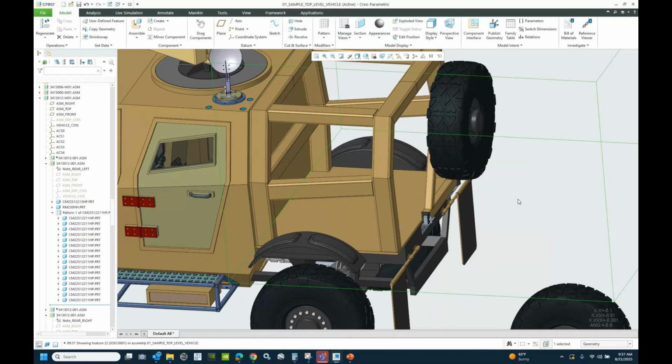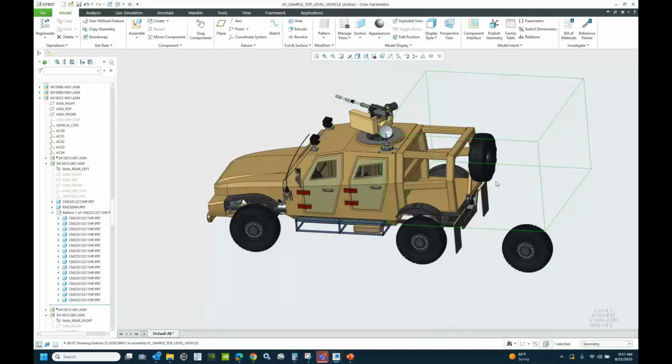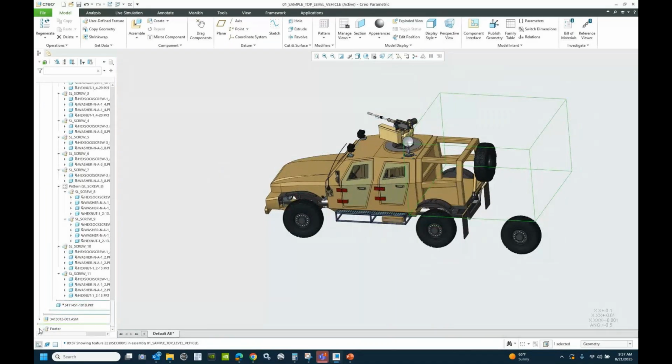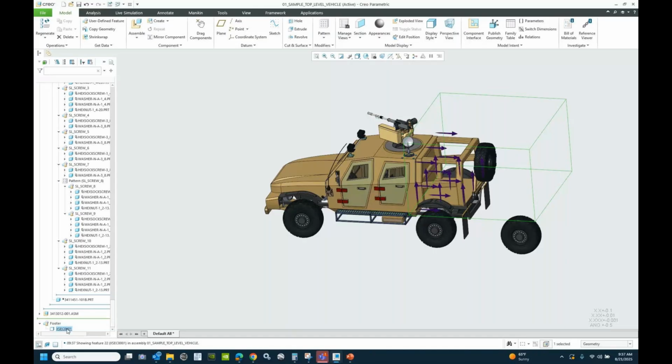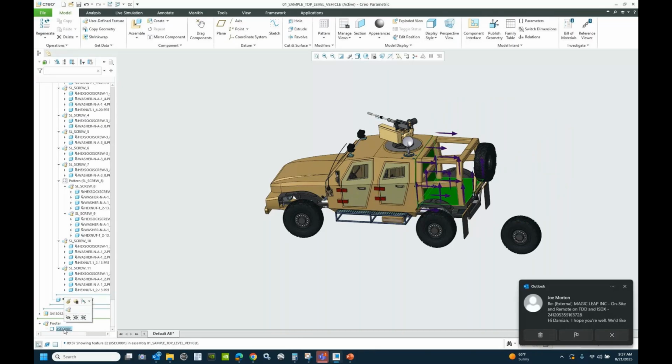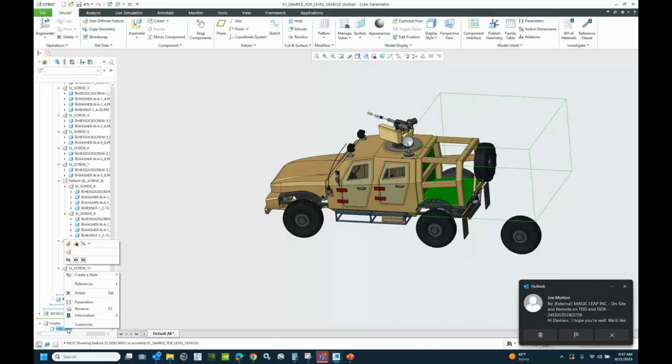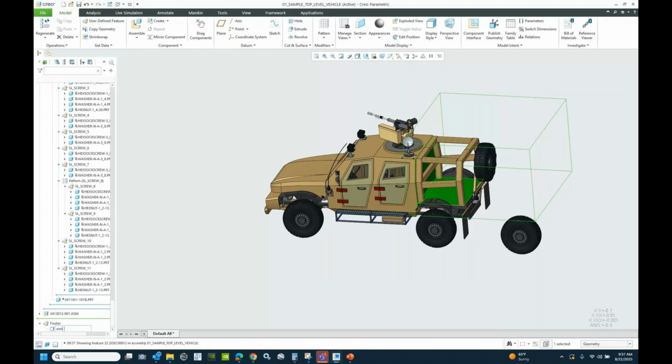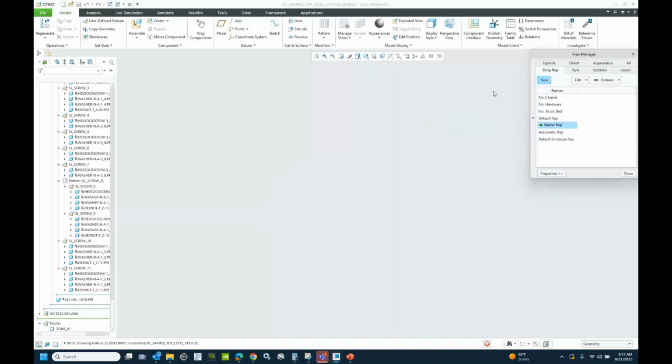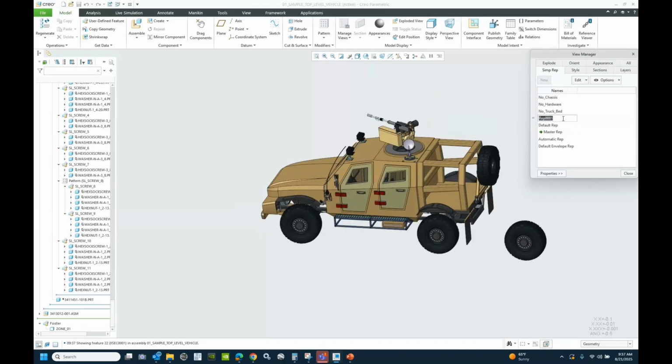Now this goes into my footer where my cross sections would typically be, and there you can see that zone, right? If I pick on it, you can see what's going on there. Then I'm going to change the name of that zone, and I'll call it zone underscore 01. I could give it something more explicit, of course. I can name it anything I want, right? Then I'm going to create another new simplified representation, and I'll call it zone underscore 1.